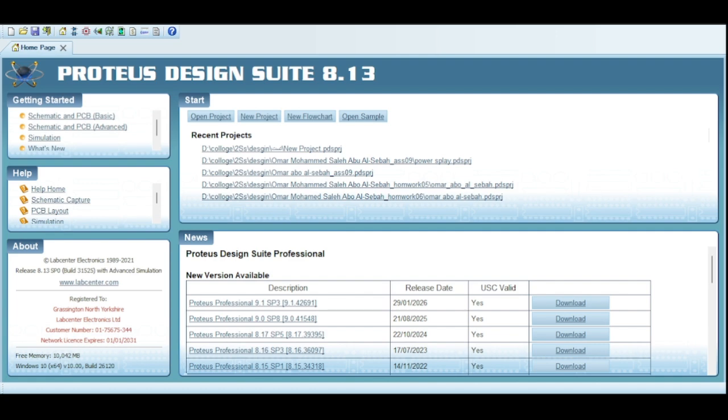So I'm right now gonna take you from a new project. I just select the folder that I am gonna put the project file within. So let's get started. I'm gonna create a schematic from the selected template, next, and yeah, we need to create a PCB layout, next, and now frame project, finish.